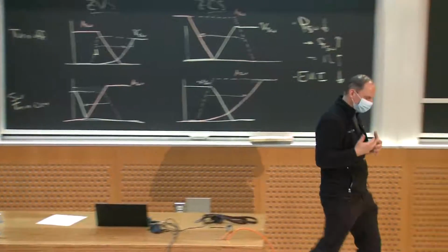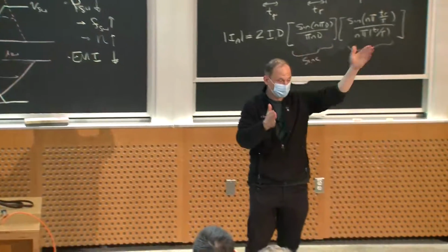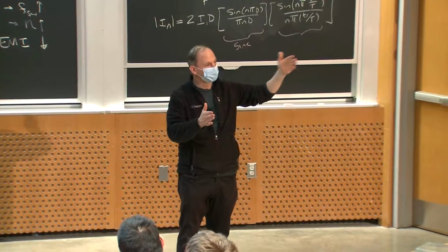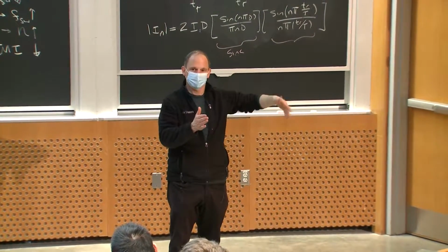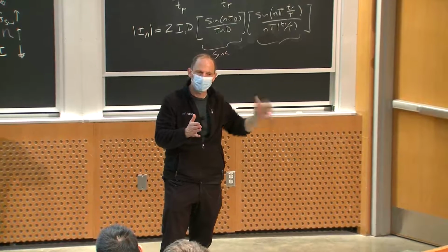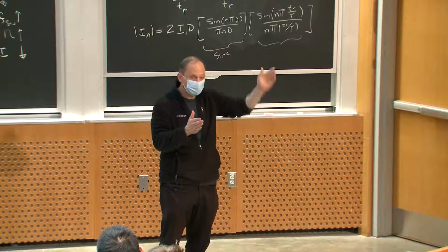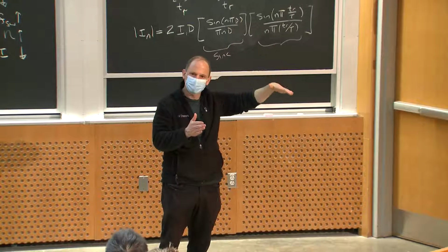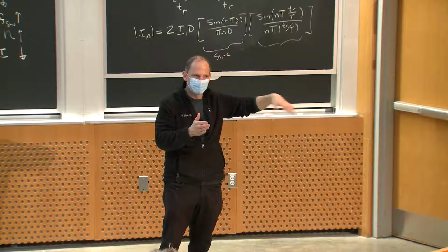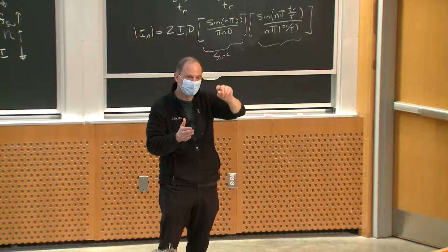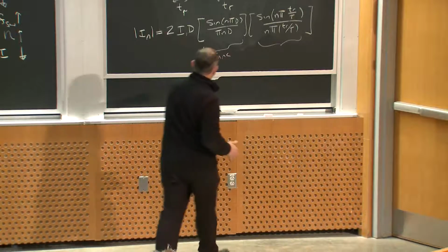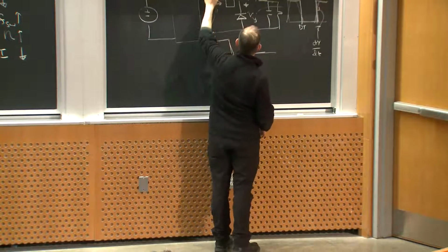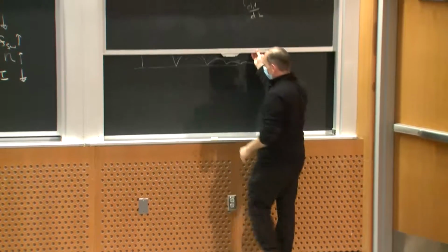What I'm trying to say is, where is the energy content in my square wave waveform? Right? It's sitting at a bunch of harmonics, okay? And I'm not really worried about the individual harmonics. I'm just worried about how the envelope of those harmonic amplitudes falls off, okay? So an individual harmonic might be really low, but it will be no bigger than the envelope dictated by the sinc function.